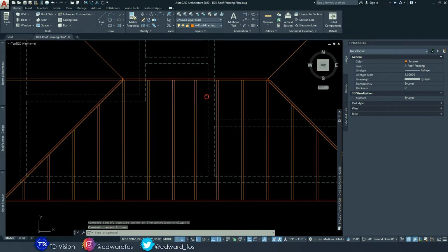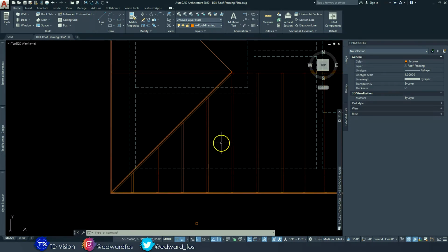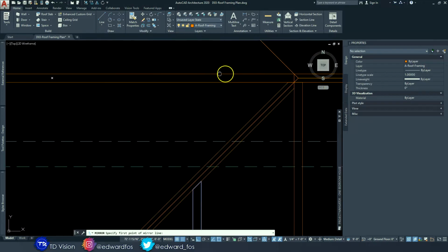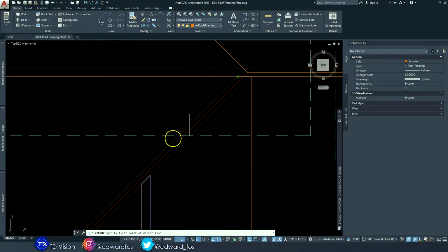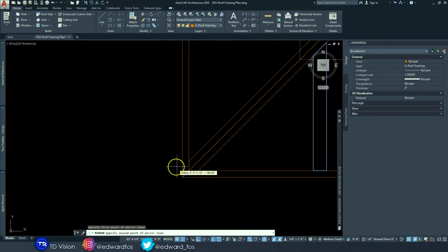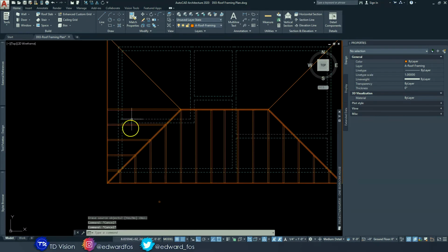All right. So bear that in mind. All right. So once we get that, what I'm going to do now is to do some more mirror. So I'm going to actually mirror these guys to fill this gap right here. How you do that? All right. Check this out. Mirror. And this time we're going to use this 45-degree center line as our mirror line. So we're going to click in the center there, drag it down to this corner. And just like that, we're going to hit enter. And now we have the next 1/8.